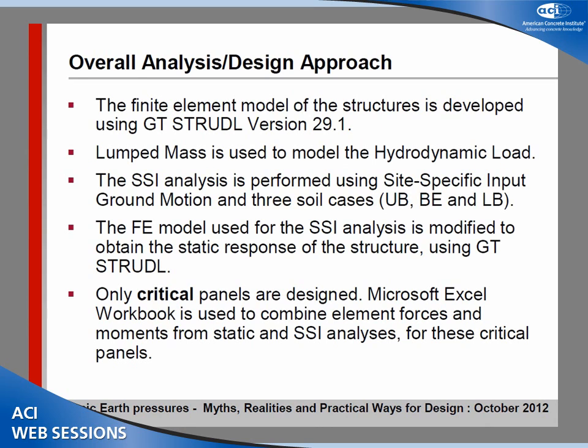We created a finite element model of the structure in order to model the fluid structure interaction effects. Rather than using fluid elements, we use a simplified model, and I will show that the simplified approach was matching quite okay with a more detailed analysis. Some of the reasons for this is that the software that is used for soil structure interaction analysis doesn't have the capabilities of actually accounting for fluid structure interaction.